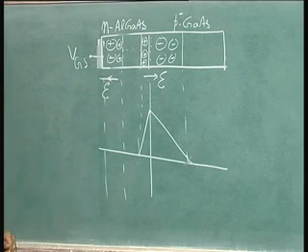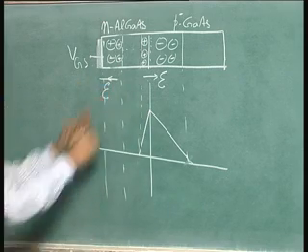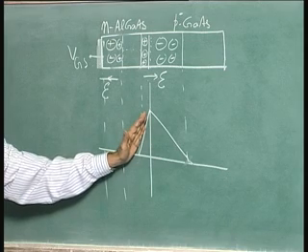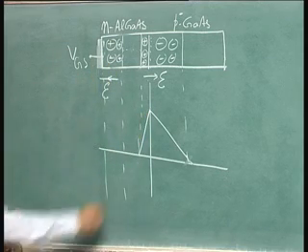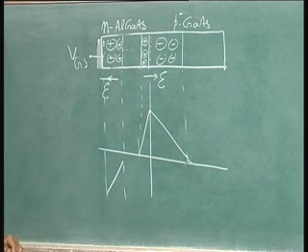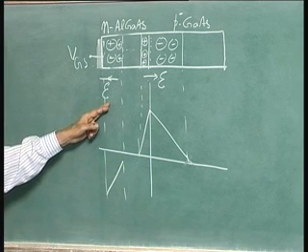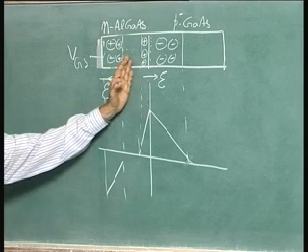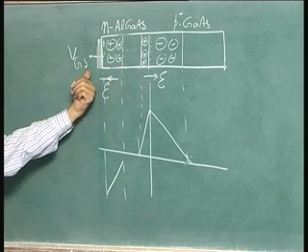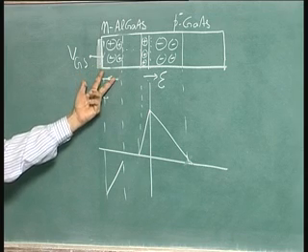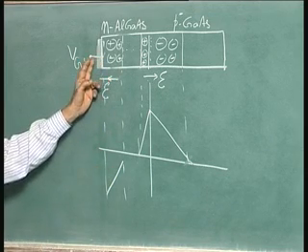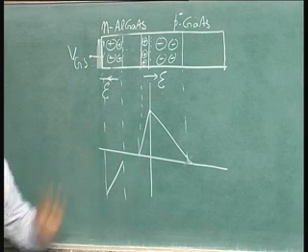So, you will have the electric field actually like this. The slope of this electric field will be parallel to that; the electric field slope depends upon doping concentration, which is the same. So, you will have actually a line like this at this point. Suppose the depletion layer moves further, when will it move? When I keep on increasing the voltage negatively more and more. When you do not apply any voltage, it is like this. If I increase this VGS, the depletion layer will keep on moving.